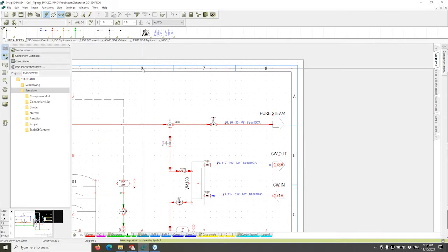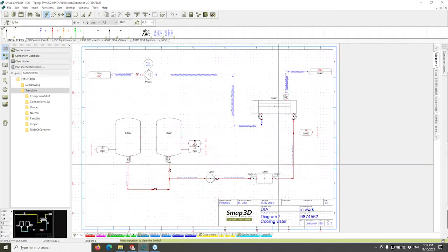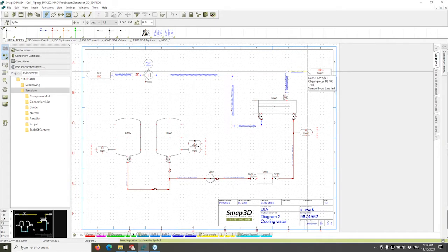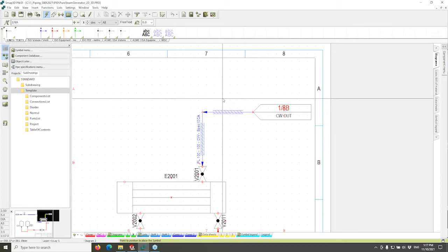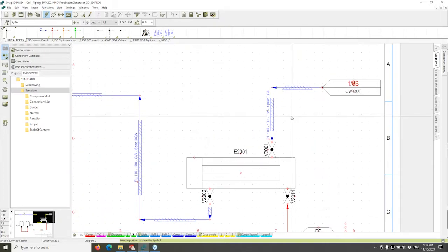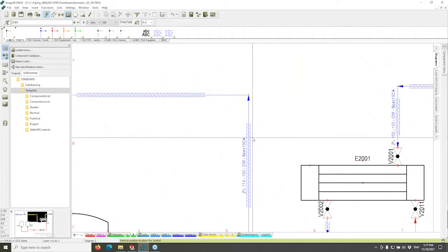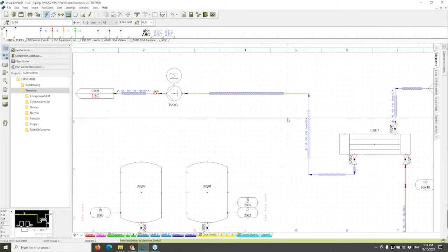And if we look up here at the top, we'll see how it's divided into numeric columns and alphabetic rows. And so we don't even have to navigate ourselves. We can just double click on that and it will put your mouse cursor on where that pipeline continues on, whatever page it is. Is it page 2 or is it page 62? So being able to trace back your steps is much easier with this intelligent linking back and forth.